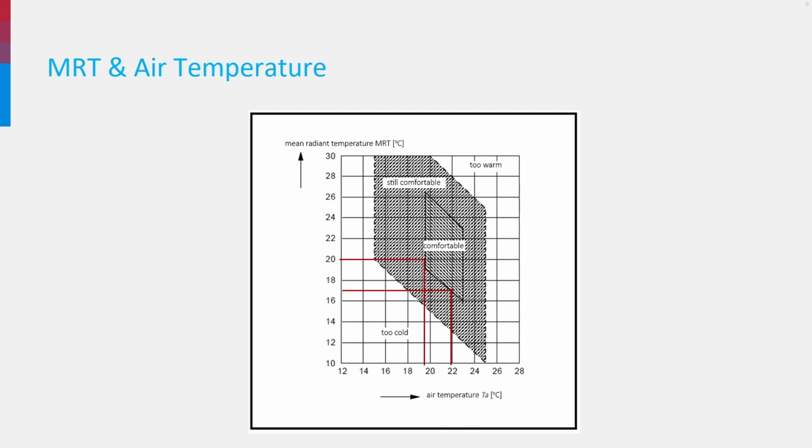Surface temperature of walls and windows depends strongly on the insulation. In a well-insulated building, the surface temperatures during the cold season are higher than in poorly insulated buildings. This results in less transmission losses and therefore less heating energy. Furthermore, because the MRT is high, the air temperature can be lowered, decreasing even more the transmission losses and the heating energy.